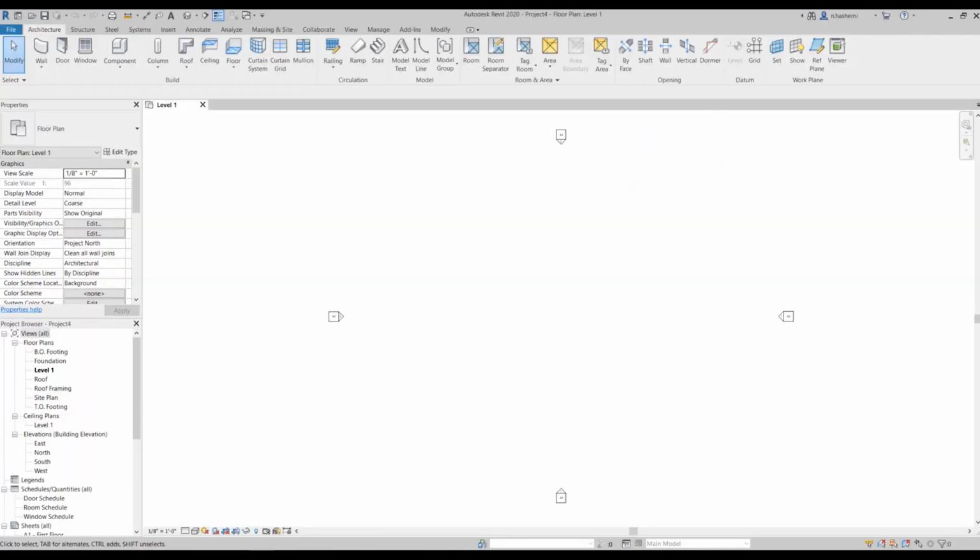Okay, so in Revit, there are two main ways to create a stair. One, which is older, is a stair by sketch, and the other one is a stair by component. Sometimes you may start with a stair by component and then convert it to a stair by sketch. Revit used to have a stair by sketch and component as two separate tools. However, they are combined right now. So let's see how we can create a stair.